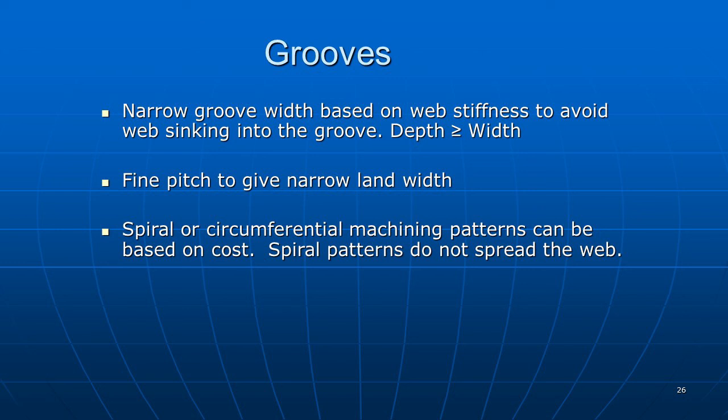Typically, you want the depth to be a little bit greater than the width. Fine pitch is good for that. I've seen rollers where, as you run your finger across them, it's like running your finger across a phonograph record. They're very fine pitch grooves machined into them. And whether they're spiral or circumferential or axial is just a machining question. They all do the same thing: get rid of the air.